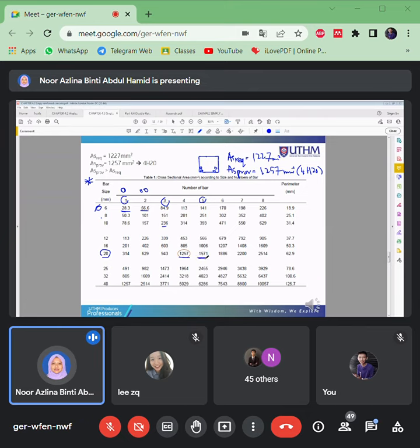This 1571 can be accepted because it is more than the AS required. But you also need to be concerned about the number of reinforcement bars. If 5H20, with the AS that you provide, is 1571, you have to add more reinforcement. So it might become crowded.